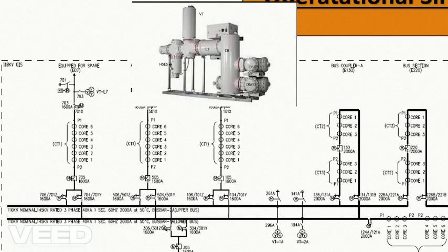This Q9 has to be closed. This is called Q9 because there are some standard designations. I will tell you. This disconnector is Q1. This is Q2. Q1 for bus bar 1, Q2 for bus bar 2. Q9 is the line isolator, and Q8 we call the high speed earthing switch.